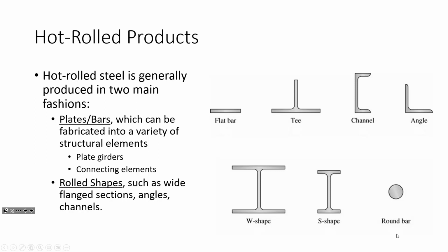Wide flange shapes, their geometry is more optimized to handle compression and flexure and things like that. And so W shapes are the more common product that we use for most commercial steel construction, period. So W shapes are really what we're going to use. So you'll probably hear me refer to W shapes much more than I say the term I-beam, okay?